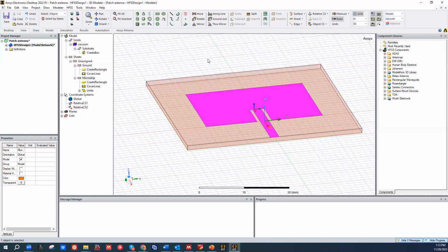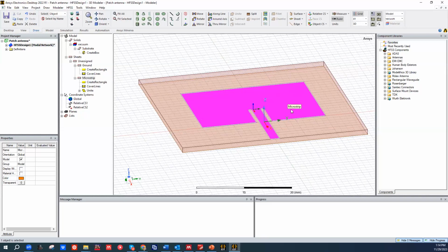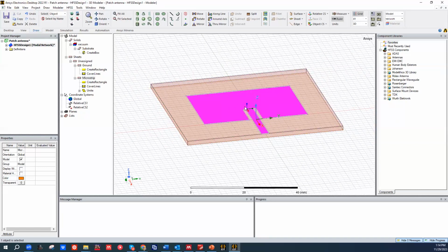And this is a good approximation in the high frequency case, for example, in this gigahertz frequency range, because the field virtually doesn't penetrate inside the metal. In reality, it penetrates by maybe several hundreds of nanometers, but compared to the actual size of the structure, which can be hundreds of micrometers, it is nothing. So virtually the field doesn't penetrate inside the metal, so we can use them as a perfect electric conductor.